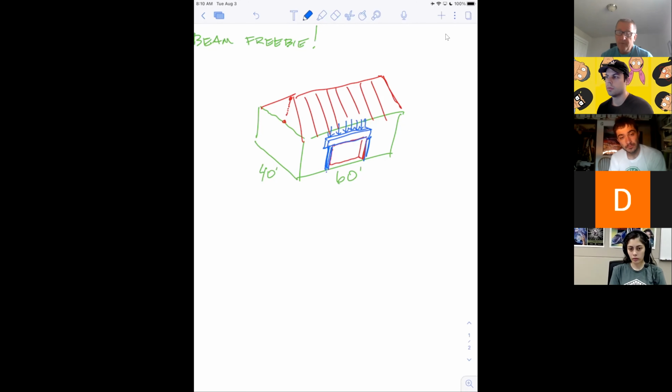And now if that beam had, like yesterday, 1,400 pounds on it, does it make sense that would put 700 pounds here? And does it make sense that could actually pierce like a pencil down into the dirt? So you actually got to put a foundation, like a snowshoe effectively, something on the ground, because it might push into the dirt. And so that's kind of the concept. And so now, does it make sense, however, that the snow that's on the back side of the house doesn't rest on that beam? That beam doesn't carry the entire roof, it carries part of the roof.